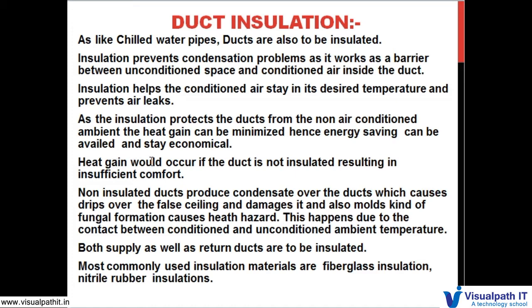Heat gain would occur if the duct is not insulated, resulting in insufficient comfort. Non-insulated ducts produce condensate over the ducts, which causes drips over the false ceiling and damages it, and also mold, a kind of fungal formation, causes health hazards. This happens due to contact between conditioned and unconditioned ambient temperature.